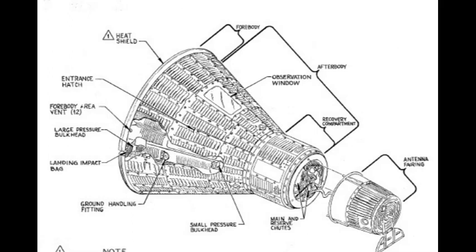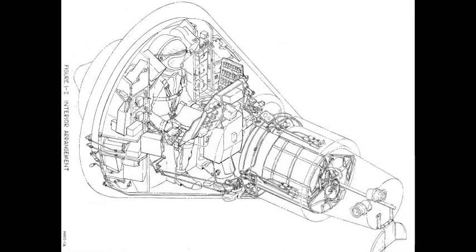Either of two interchangeable types of forebody heat shields, namely the heat sink and the ablation shield, is used on the capsule. The heat sink is constructed of pressed beryllium and is designed to absorb heat. The ablation shield is designed to ablate heat and is constructed of fiberglass shingles, radially laminated to form a smooth contour. A retrograde package assembly is attached to the heat shield by means of 3 straps. The retrograde package is jettisoned from the capsule following retrograde rocket firing, which initiates capsule reentry.